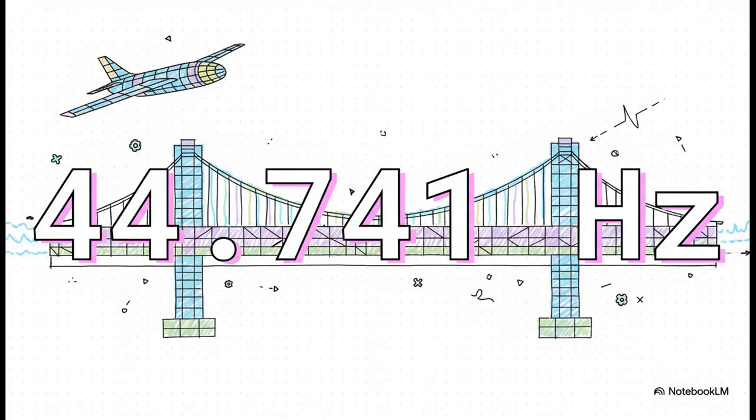And let's look at a real concrete number, 44.741 Hertz. Now, that might seem random, but this is the calculated natural frequency of a simple beam. Why does this one number matter so much? Because if an outside force, say wind or an engine vibration, hits that beam at exactly this frequency, it will start to shake violently. This is called resonance. It's the same physics that lets you push a kid on a swing higher and higher with those perfectly timed shoves. And for an engineer, knowing this number is the difference between a stable structure and a catastrophic failure.